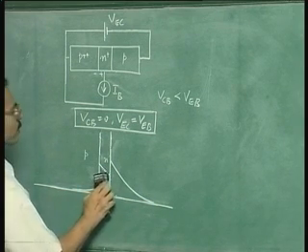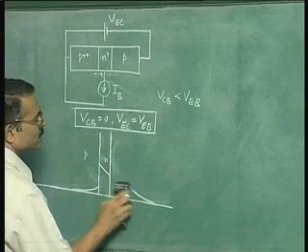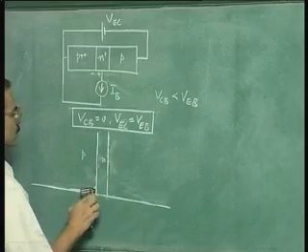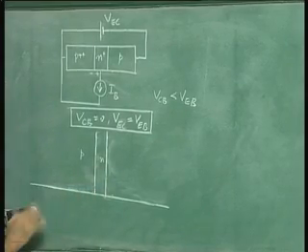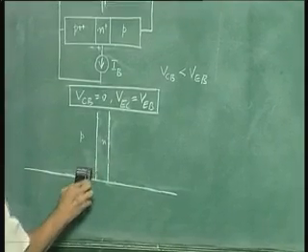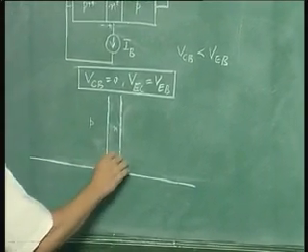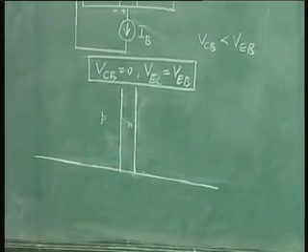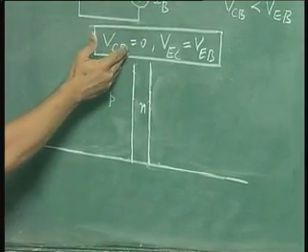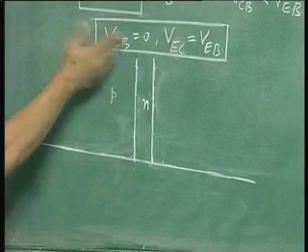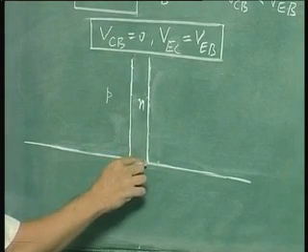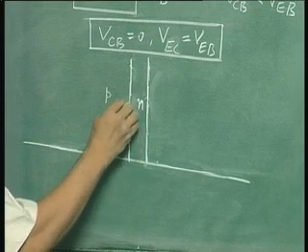So again now we will rub this excess carrier concentrations and we will redraw them for the condition that we now have. Now it is very easy to draw the excess carrier concentration for this condition, because we have actually analyzed the transistor in the beginning for this condition, collector base voltage equal to 0. So 0 collector base voltage means the excess carrier concentration is 0 here.